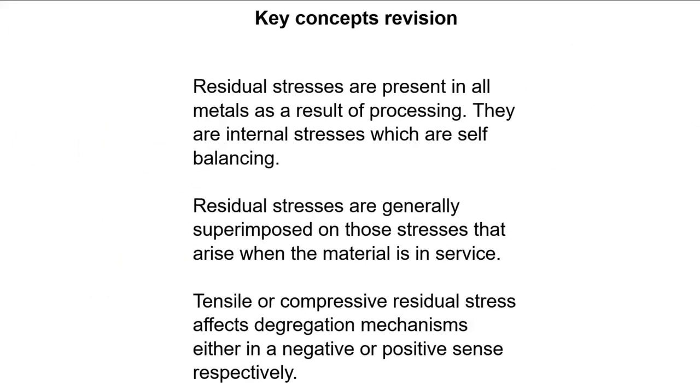So in this part of the lecture, it's been shown that residual stresses are generally superimposed on those stresses that arise when a material is in service. Residual stresses can either be beneficial or detrimental to the integrity of engineering components. Surface treatment techniques can be used to produce compressive residual stresses at the surface of components that are subject to fatigue loading or prone to stress corrosion cracking. Other abatement techniques include post-weld heat treatments, but these need to be carefully applied in conjunction with modifications to the originating process in order to be the most effective.